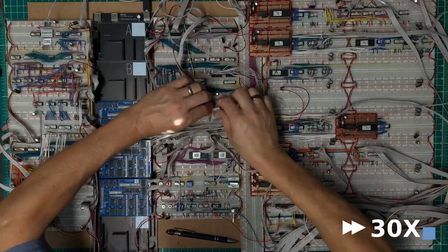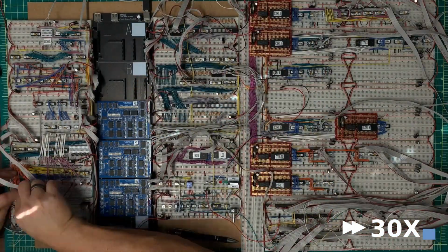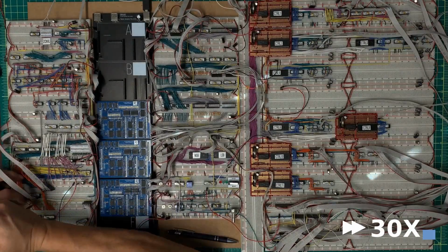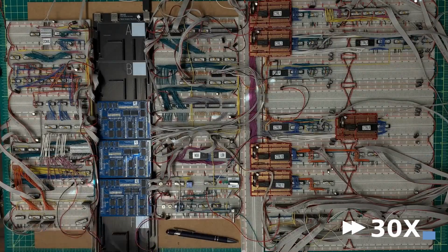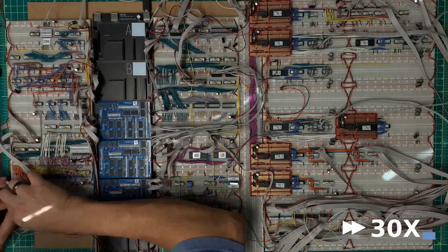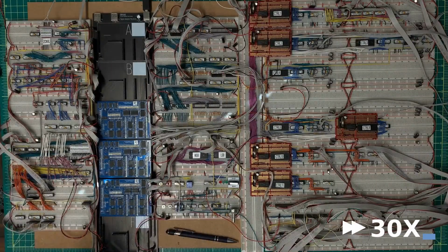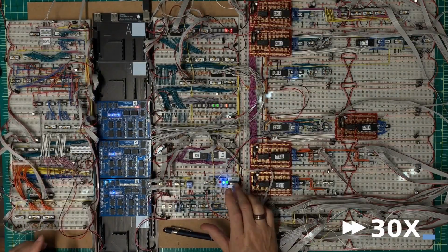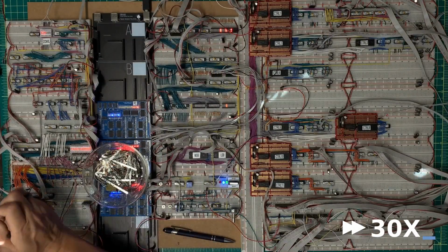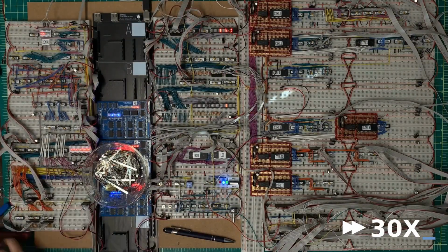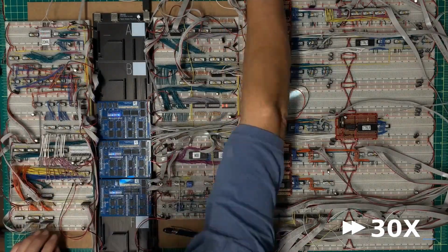Okay, the fetch register assert onto ALUB and the ALUB line drivers on the ALU Adder both are very quick swaps. The ALUA line driver, just to condition those inputs, takes a little bit longer. Ultimately, I end up shorting power to ground for a short period of time. That creates a situation with the reset that takes a few power cycles to resolve. I'm not exactly sure what's going on with that, but I'll have to keep a close eye on it as we test.